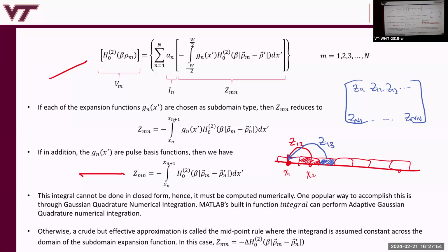Tangential electric field at that point is zero. The tangential electric field at this point has to be what? It's zero, because that's what this equation is enforcing. So what is the tangential electric field at that point? The incident field plus the scatter field due to the rest of the structure. All this current radiates. You have to add up the electric field due to all of this current at that point to get the true total electric field there. That has to be equal to 0.